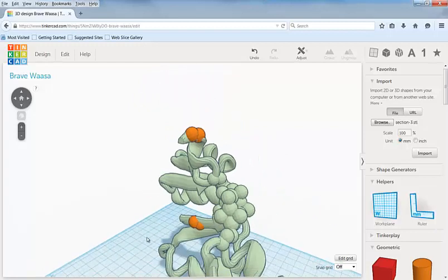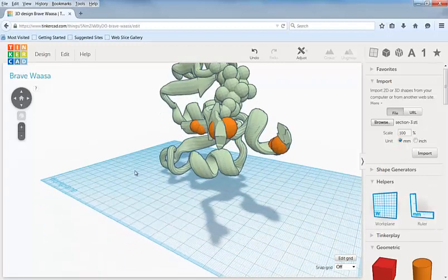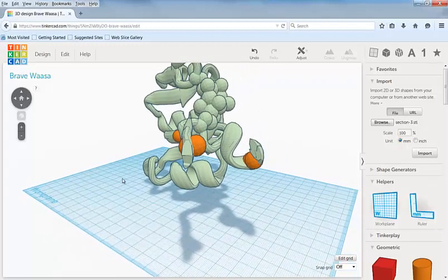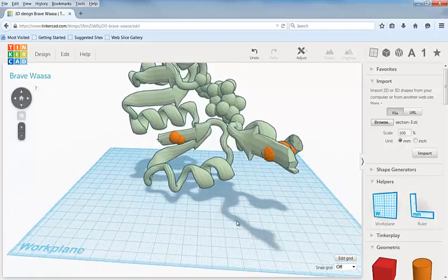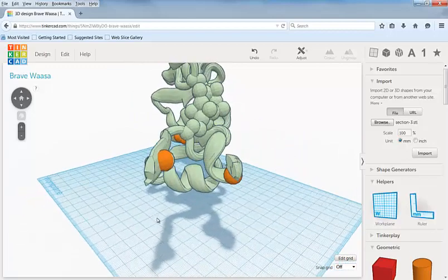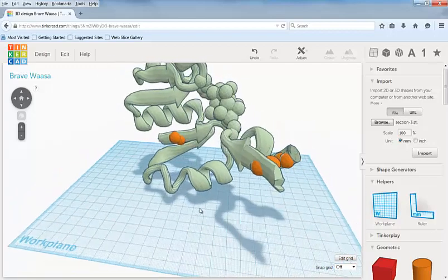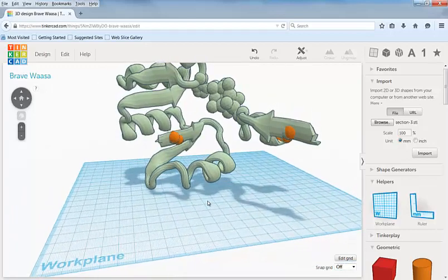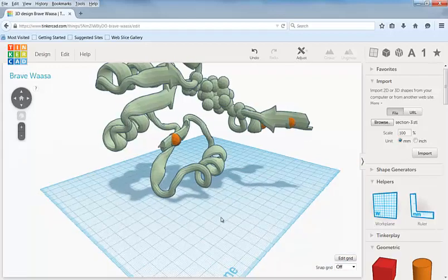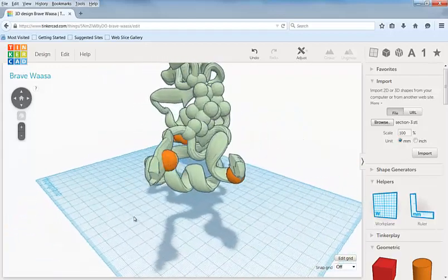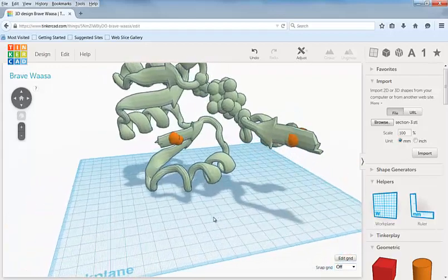One thing, you've got to know how to use Tinkercad. If you hold down the Shift key and your right arrow key, you can change the point of where your camera setting is at, so where you're viewing. You can move this around using those. You can also hold the right key on your mouse and move it around here. If you've got a scroll on your mouse, you can scroll in or out. So it gives you quite a bit of options, but you're going to need to be able to position yourself so you can see things.